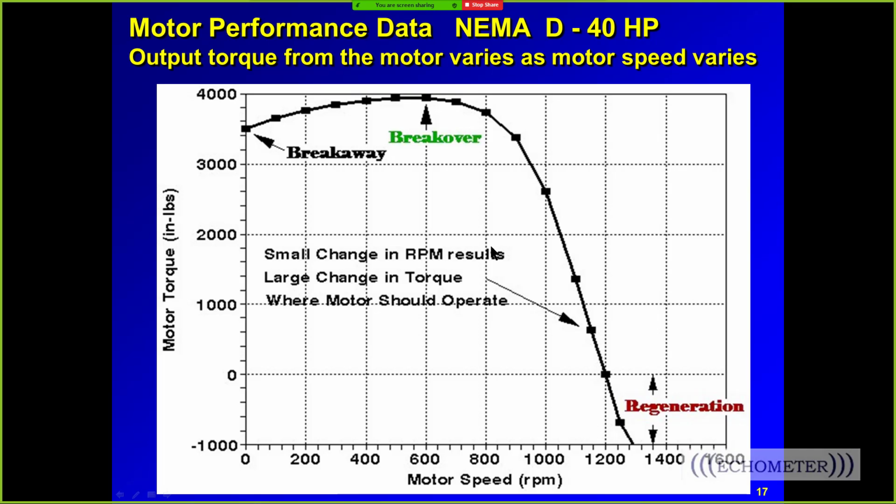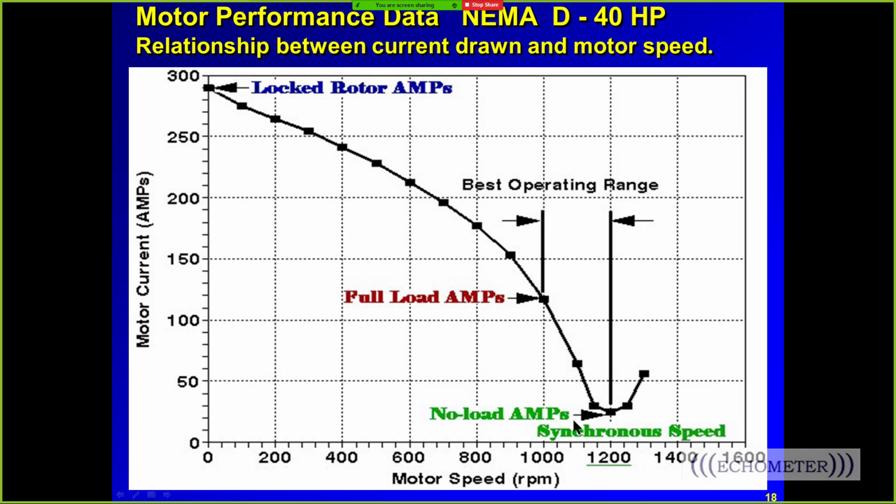And that's the way the motor behaves and the power behaves throughout a stroke. Now the current is a little different. There's a thing called locked rotor current. If you were to set the brake and turn the motor on, then the current is a maximum, and it doesn't really drop off if the motor is locked with the brake. But if it's not held with the brake, then the amps quickly drop from the locked rotor current down to this normal speed here. There'd be no load.